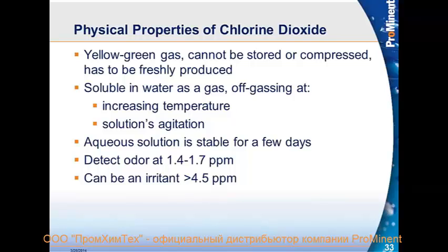And the solution is actually stable for a few days, so that's why it's used a lot in vegetable and fruit washing, because it lasts a little bit longer than chlorine does and does not leave any taste or odor concerns. So it's good for those type applications. You can detect the odor at under 2 ppm, so it does give off an odor, and it can be an irritant above 4.5 ppm.